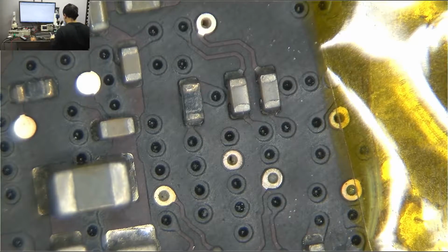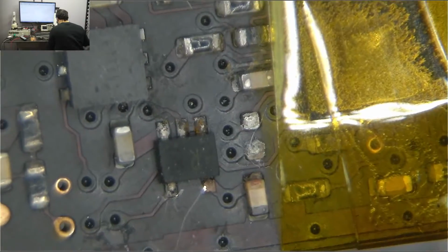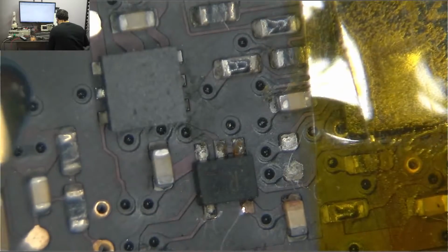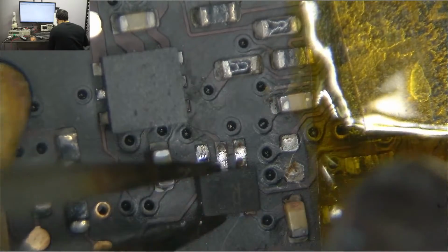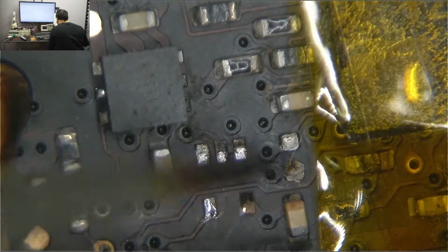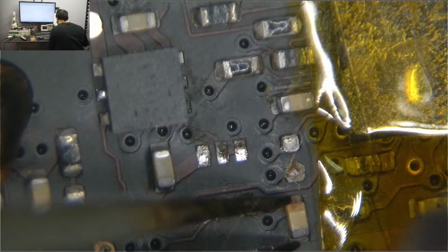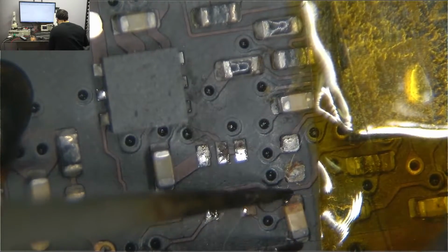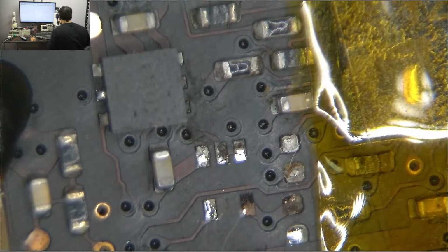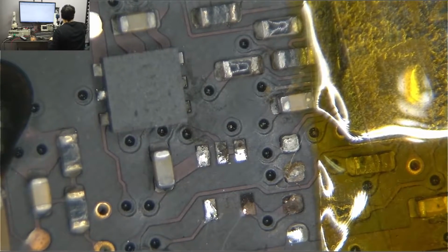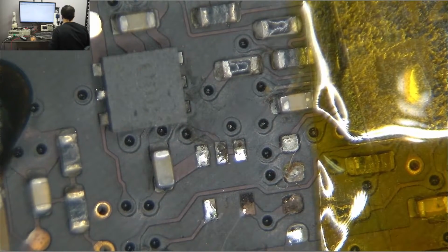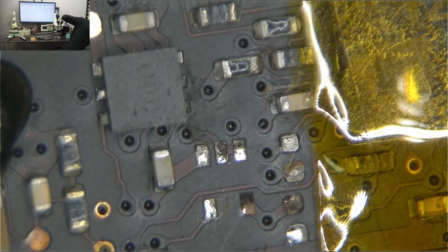That little bypass capacitor looks like crap. And there is also the actual U6901, which itself looks like crap, and that pad looks like crap. So I'm just going to take those off. And I don't even care if that logic gate was good. For all I know, that logic gate was good, and the only issue I actually had here was that the pad on the board was just nasty. It really could have been an issue of the actual pad.